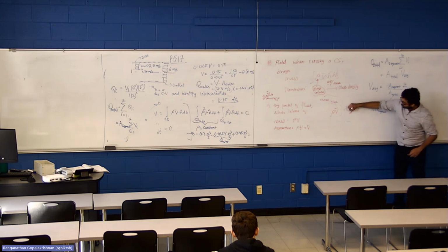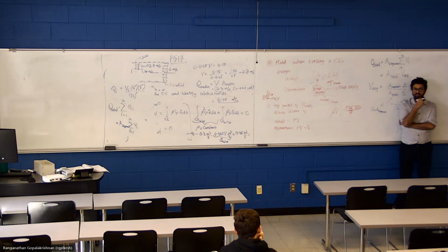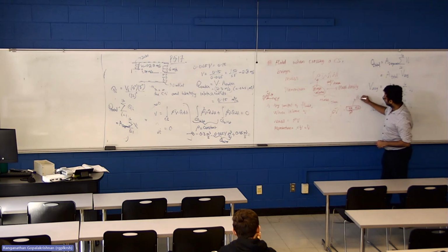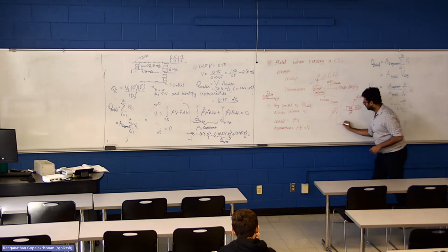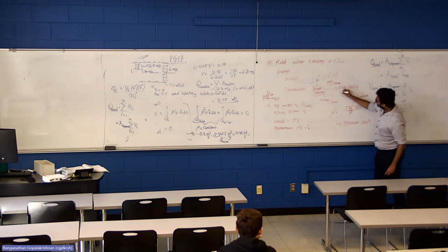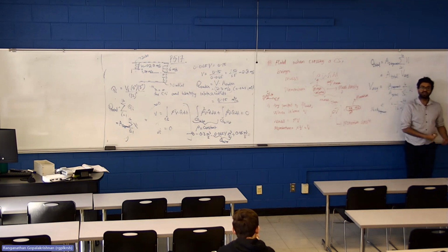What is the quantity in the numerator? Do we recognize this? What is mass times velocity? Momentum, right? So this quantity is the same unit as momentum. So rho times V can be thought of as momentum density. Just like you think rho is mass density, rho V is momentum density. It's the amount of momentum you transport across the surface when you are flowing.